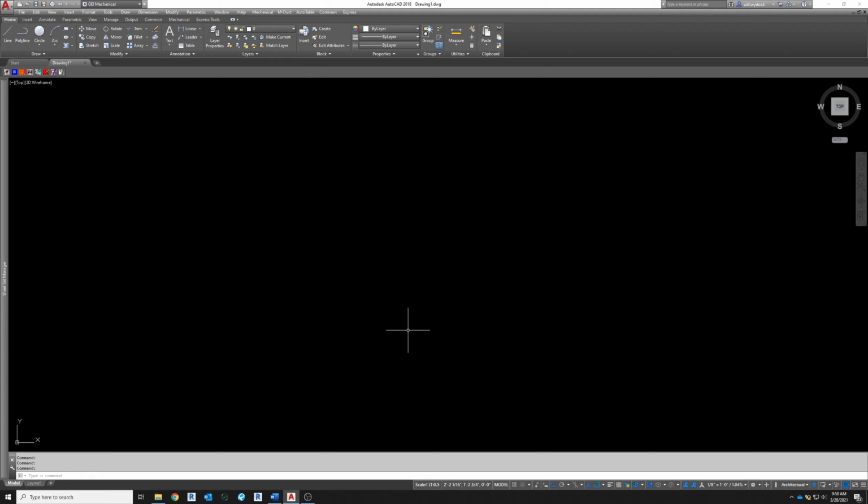Now the second part that we need to do: we got text styles right, now we have to make sure that it shows right. In AutoCAD, our plotting is based on line colors. So for a standard schedule, the border around the title and the border around the whole schedule is cyan. Everything internal is white. Text is white. We need to make sure that information is also set up on your computer. All this stuff that I'm doing now is one time setup. We don't have to do this every time you start a project. It's just the one time.